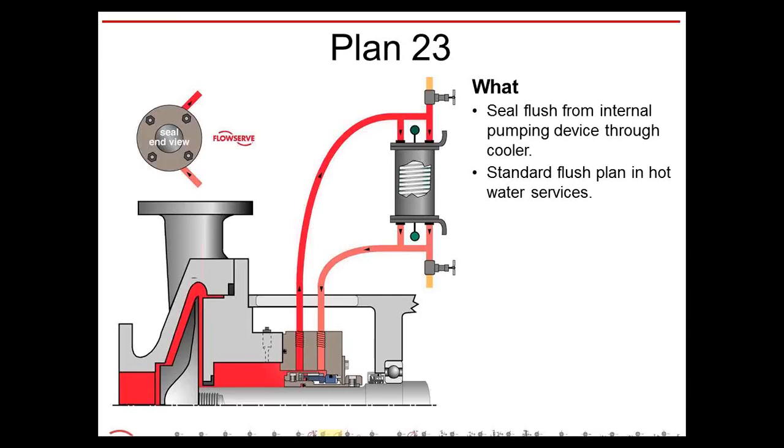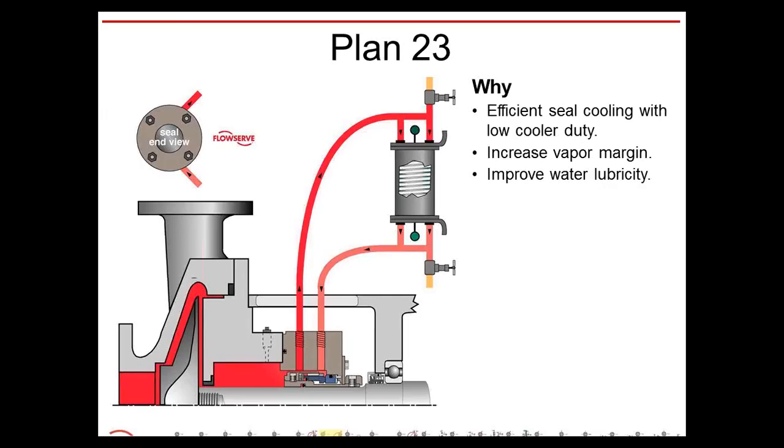You want to be able to cool that water down and get those lubricating properties back in your system. Now these are efficient ways of cooling the fluids. They increase the vapor margin because you're cooling the fluid down, and it improves the water lubricity, again, because you're cooling the water down, or any fluid for that matter.